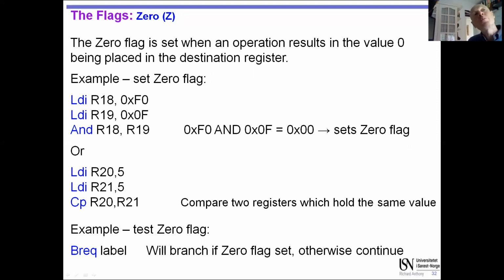You might say, okay, well, compare these, and if they were equal, do something. So if you follow this compare with branch if equal, what's going to happen is when that instruction is executed, the zero flag will be part of its behavior. It will look at the zero flag and decide whether to do the branch or not. And that means whether it will take the program counter +1 or the program counter offset to this value, which is the new area to go to.